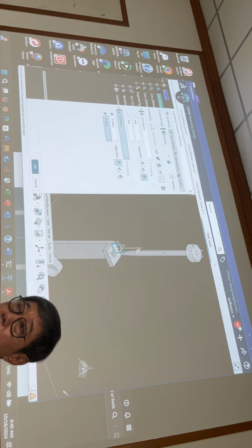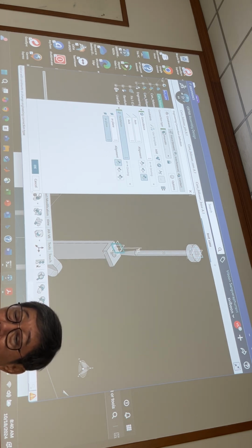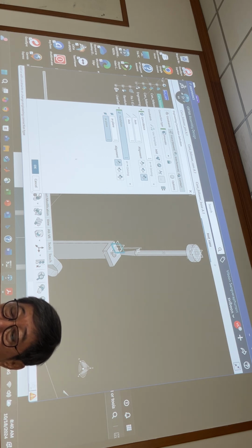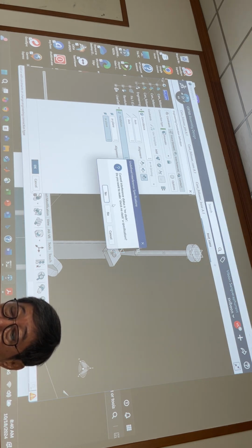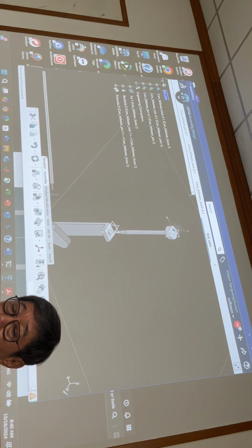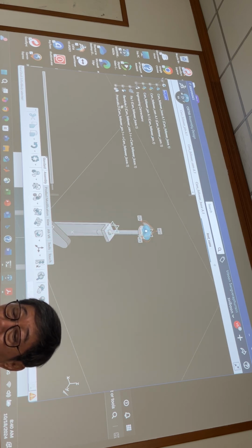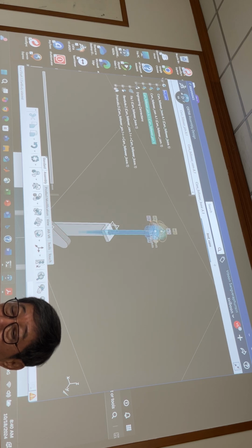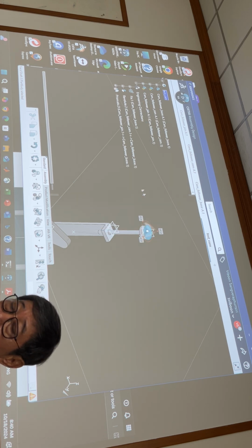See? Parallel. Okay, now it changed to prismatic joint, you see? Automatic change to prismatic joint, from cylindrical previously, right? Okay? We have this one. Going to check for crash? Yes. Okay. I can move this one now. Because it's a prismatic joint, right? This one is allowed to slide along this one, but you cannot rotate. You see, you cannot rotate. No way, because you already set the constraint.